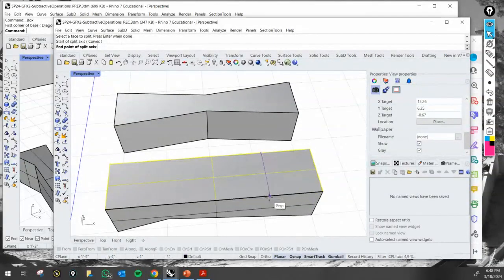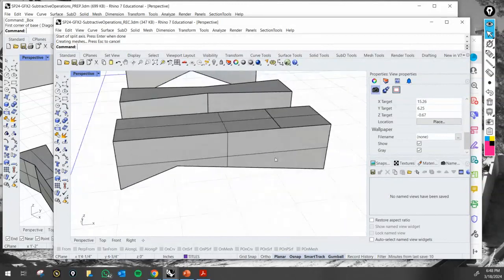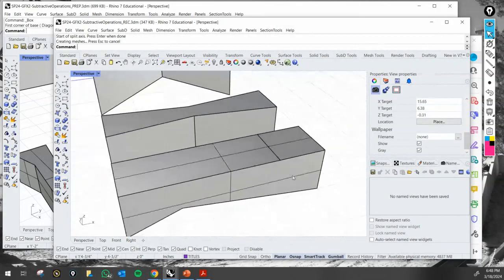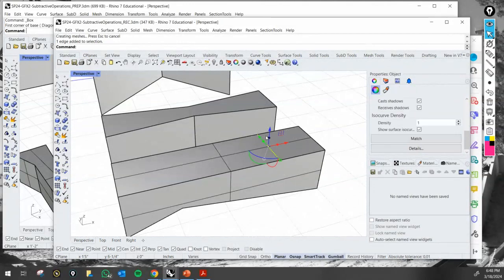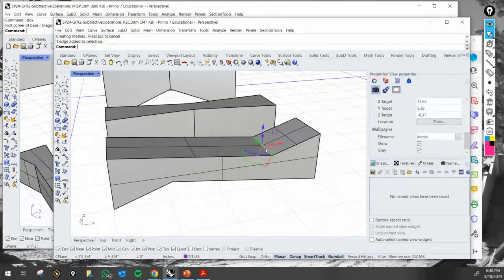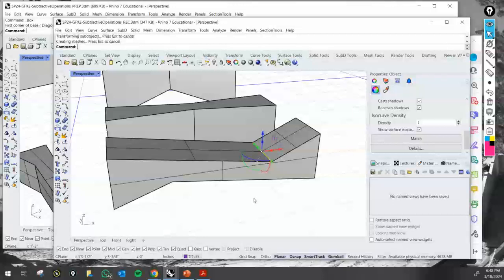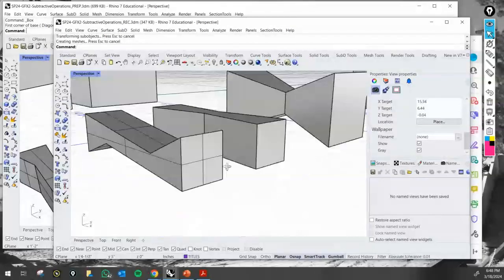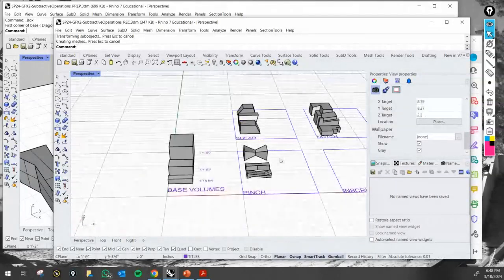In this case, I'm not using the grid snap. I'm just going off of my drafting tool aids right here on the bottom, the center, the intersection, perpendicular, and things like that. If I do Control Shift select, blue arrow, I can bring that down like that. Control Shift select, maybe be a little bit more drastic, more dramatic. I can do something like that.